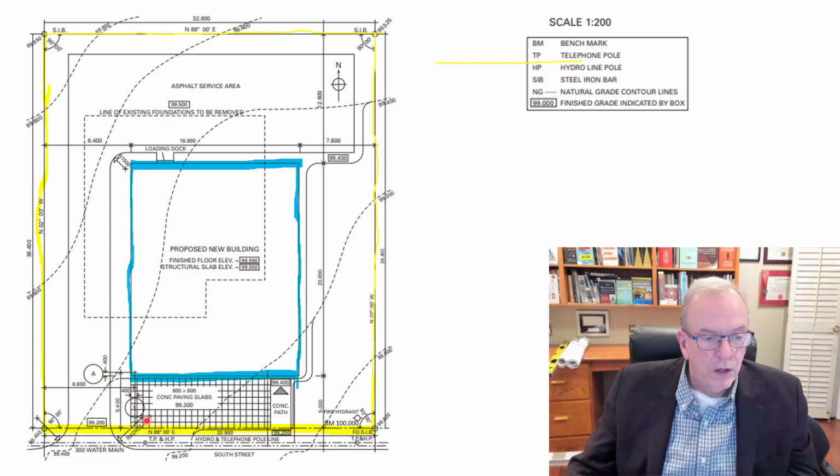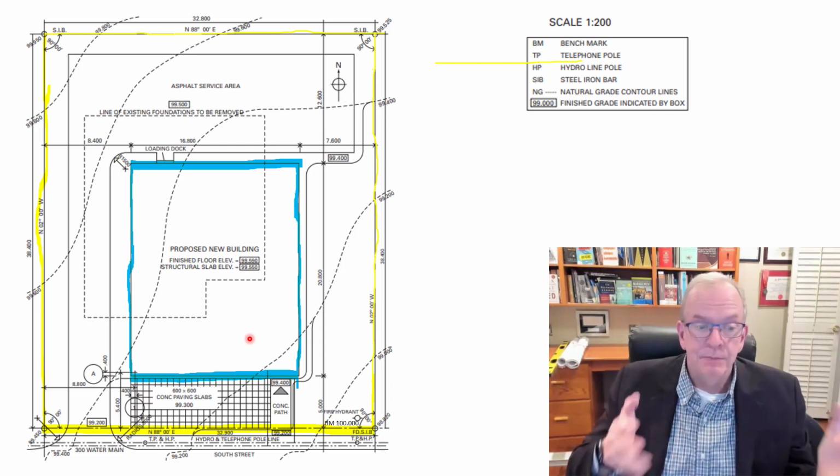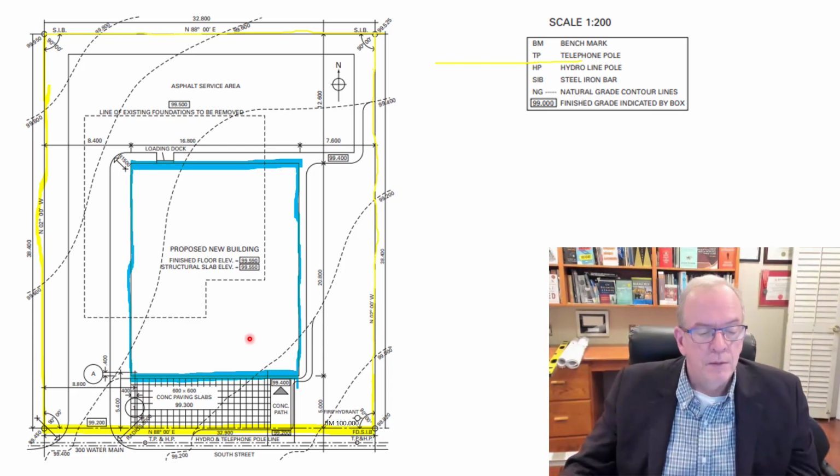And we have also here, this is showing A1. This is for an architectural grid. On the architectural drawings, you would see basically a grid layout, which is tied to the planning grid or structural grid to show where key structural elements are. And this is basically your reference point. So when you look at A1 on the floor plans, you know where this is on the actual site plan, where you typically don't need the grid because you're not doing those structural points, but at least you can orient yourself. You're always trying to orient yourself with the drawings, right?